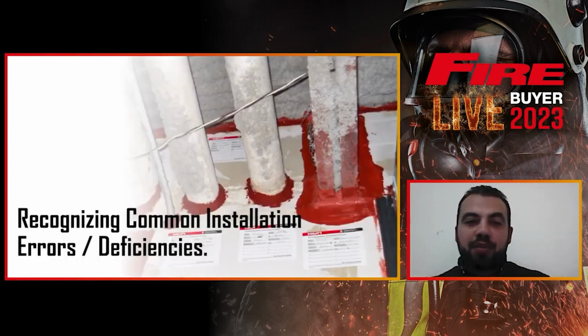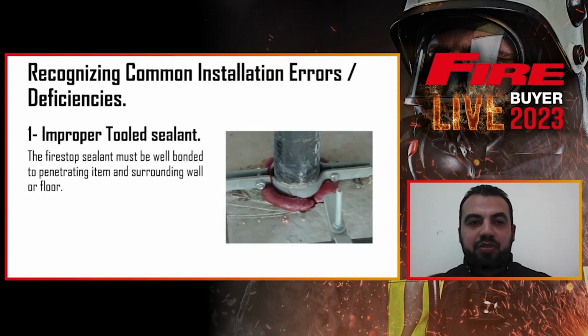Recognizing the common installation errors and deficiencies is what you need to avoid on site, and what the fire inspector needs to look at when doing inspections. The first case here is the improper tooled sealant. This gives an indication that your material is not applied with the right thickness in the annular space, and the annular space might not be filled properly.